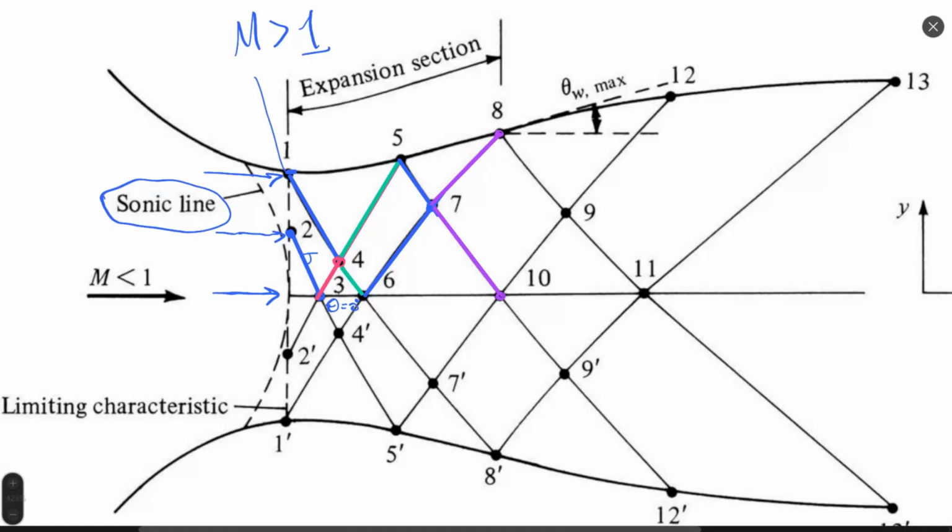If you would like to see a solution with numbers, please go to one of the videos of the questionnaire of gas dynamics where I show how the solution is obtained numerically, point by point. I show several points, I think, not all, not until point 13, because it's useless. All operations are repeated one by one, and this algorithm can be easily programmed inside the computer, a MATLAB code, or any other software, even Microsoft Excel can give us calculation of flow by the method of characteristics.